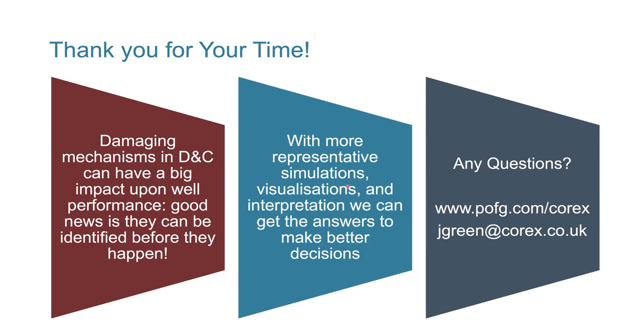If one mud is giving us an overbalance pressure of a few hundred PSI and another is giving 1,000 PSI, we should be looking at those options. So the density of the mud, including that in the test design and understanding what impact it has, is 100% important. And that's a typical thing operators look at. They look at whether there is a difference between these two SGs or densities of mud. Is there a difference when I add this drill bit lubricant or friction reducers? Do these make a difference to the mud with and without them? These are really classic questions we ask in drilling.